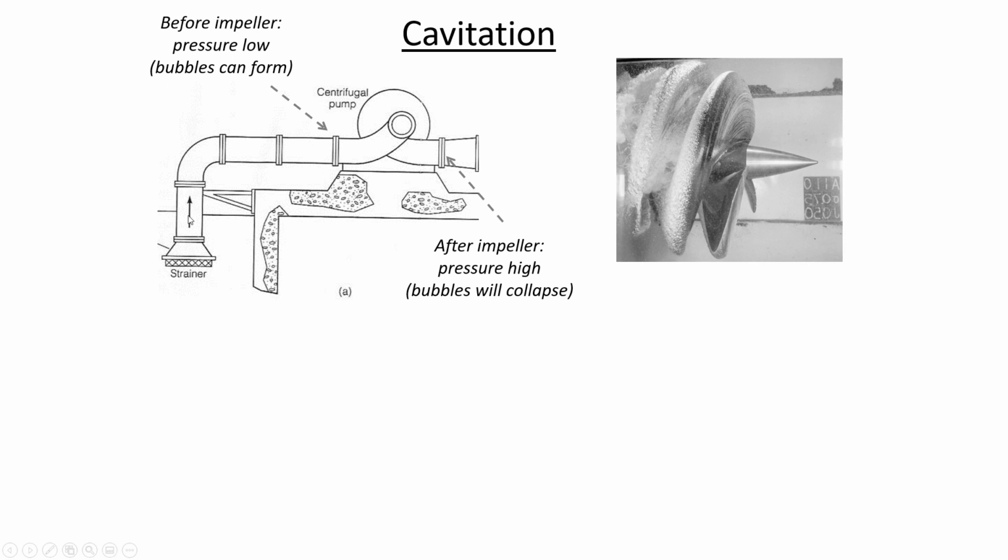I've already explained to you on previous occasions that on the suction side of a pump, the pressure is decreasing in the direction of flow, and that if the pressure gets below the vapor pressure of the liquid, those little vapor bubbles can form at the impeller inside the pump. And those vapor bubbles are dangerous because when they collapse, they send a shock wave through the water that can scour and pit the surface of the metal impeller. So those bubbles collapsing cause really high concentrated pressures that cause a reverberation in the water.